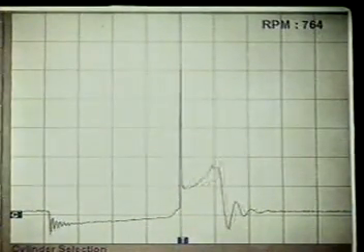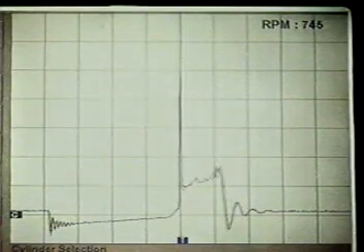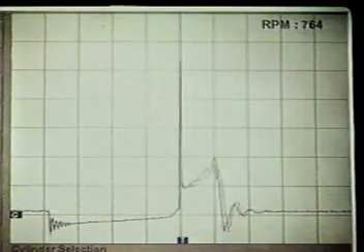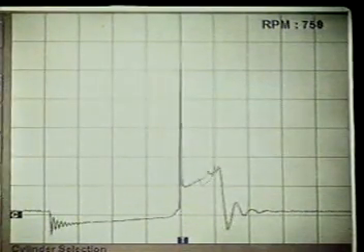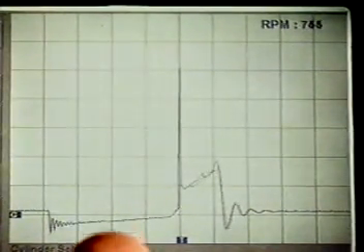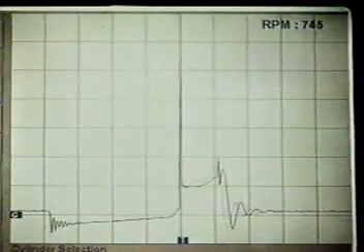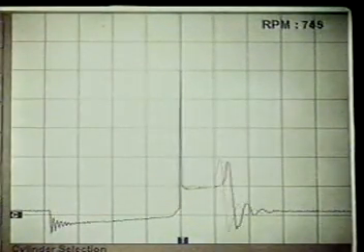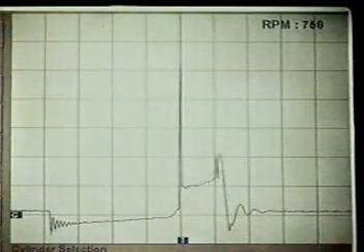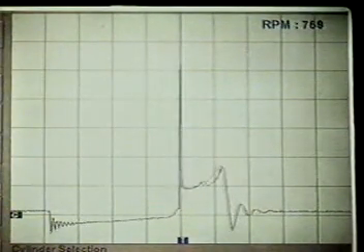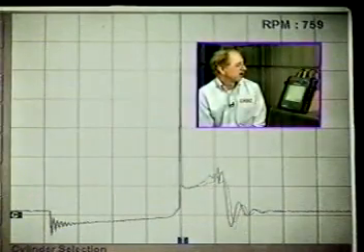Well, what you're witnessing here on a 1 millisecond time base, looking at cylinder number 1, you can see that we are barely maintaining a 1.3 millisecond burn time. Well, let's go to cylinder number 4 right through the firing order. Let's bring number 4 up here, and let's analyze the spark line. You can see that it is maintaining about a 1.2, maybe a little bit higher spark duration. It's a little bit longer than cylinder number 1 was. Let's move on to cylinder number 2.